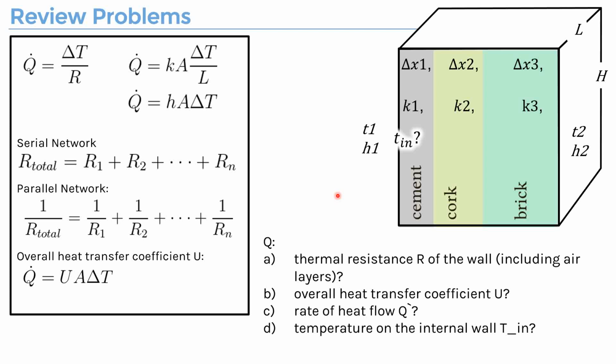So the steps to solve this kind of problem would always be, because you are given the conductivities and also the dimensions of this geometry, the only thing I need to remind you is the convection part could very easily be neglected, but it matters in the total resistances.